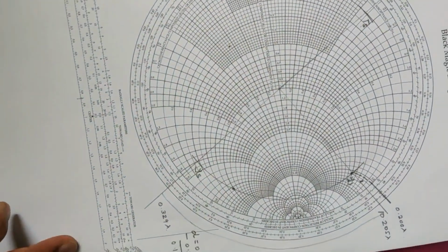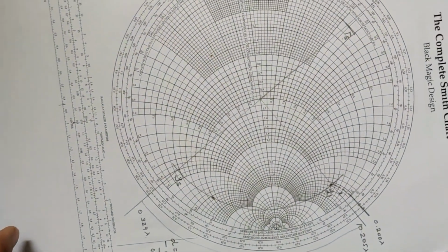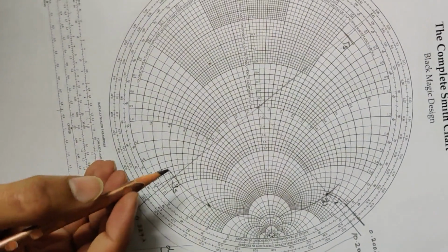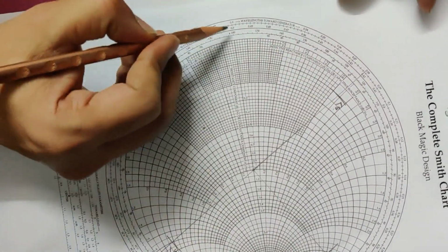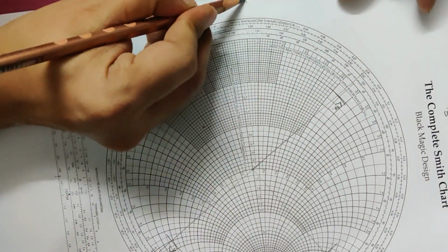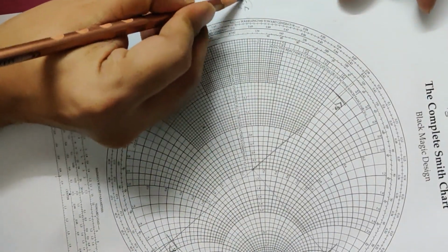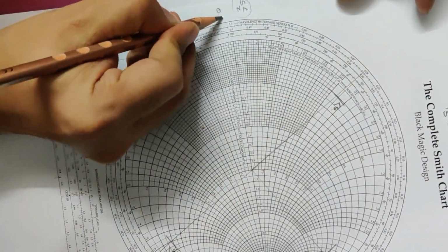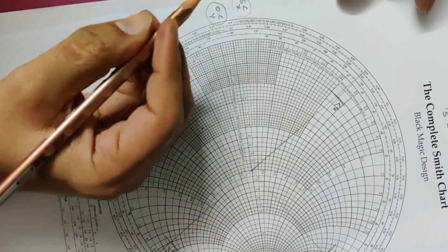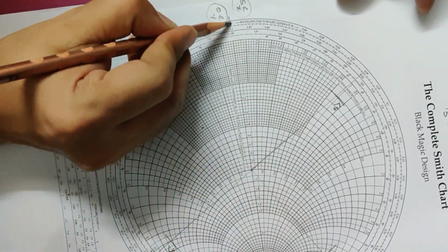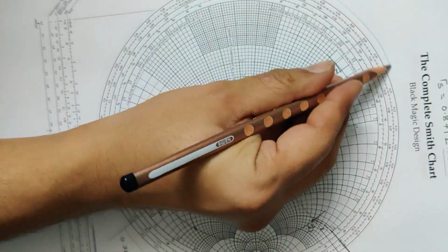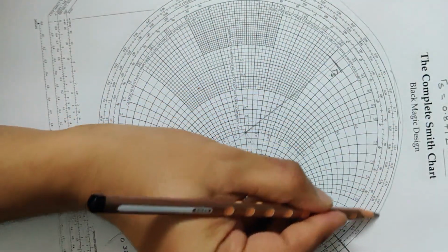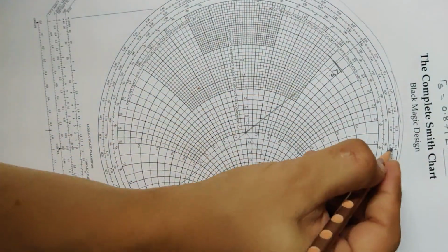Now we are designing an open circuited stub in Y. So as you know, this point is short circuited in Z. So this is the short circuited point in Z. Similarly, the same point is nothing but open circuited in Y. So one has to always measure the length from this end up to this point. And this is nothing but the length of this stub.